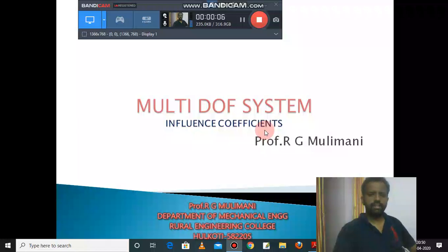Okay, it is influence coefficients. It is required in some of the numerical methods. For example, in the Dunkerley method and in the matrix iteration method, these influence coefficients are required to find the natural frequency of the systems.